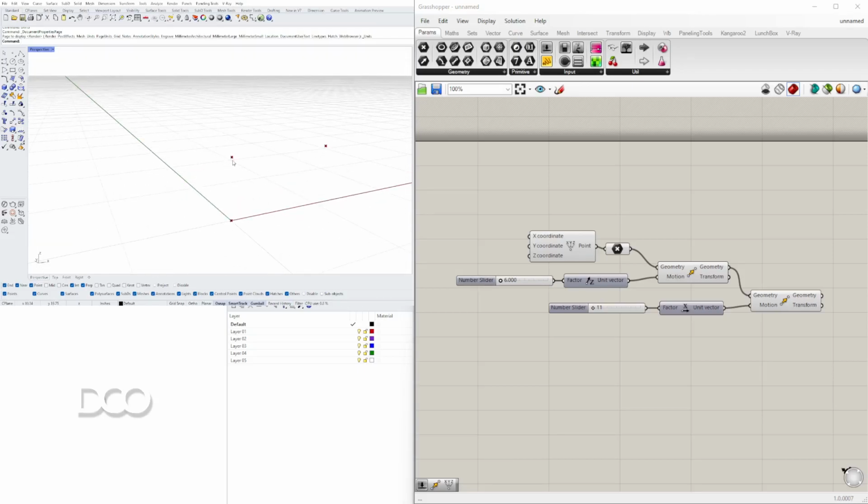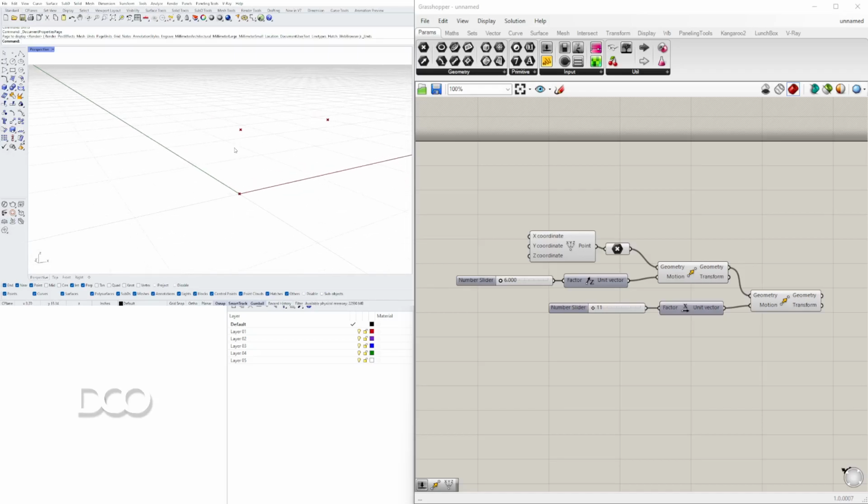Now there's different designs for nosings. For me, I'm going to create a square one. So how do we achieve this? Well, what we have to do is take this point, move it in the negative X direction and in the negative Z direction by either the same or a different amount. In this way, we have the points that create that overall form.